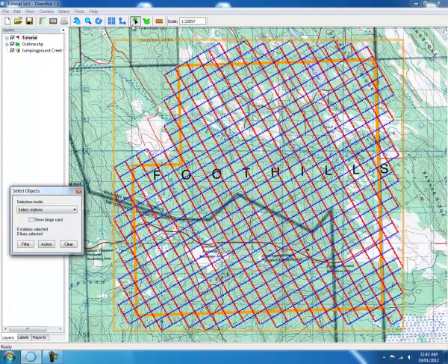Like the Select Area tool, the Select Objects tool includes a selection mode which can be used to control what kinds of objects are selected. By default, the tool selects individual stations. However, when we're cleaning up the boundary of the project, it's a bit faster if we select Complete Salvos. Click on the Selection Mode drop-down list and choose Select Salvos.